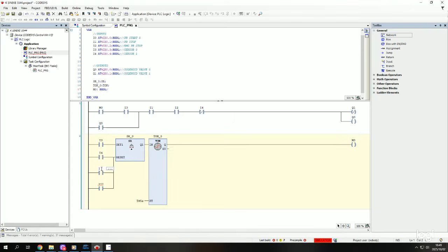So this becomes our I1, which is our stop push button, and then our I2, which is our emergency stop push button. So we have I0, which is presented as M0, memory 0. We have I4, which is this, I1 that, I2 that. Whatever you have on your ladder logic diagram, you must also have when you are rebuilding your memory side. So what's new?